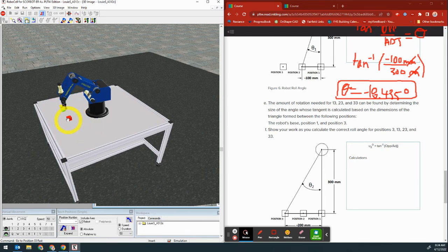So you can see right now that my robot picks it up, stacks them up, and then puts them back to their original position. Since my program does that, when I run it continuously, it recycles back to the top of my program and picks up block 2 again. Sorry, it's going to go home, start from the home position, go above block 2, come down on block 2, pick it up, come back up to the pickup position, and set it back down.